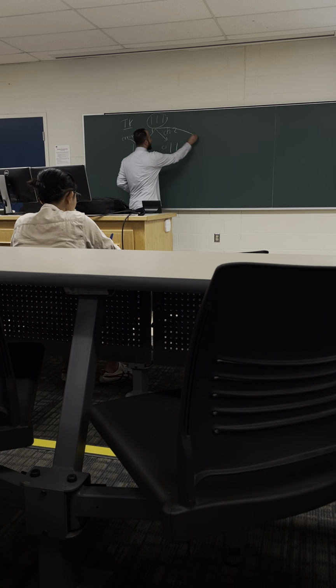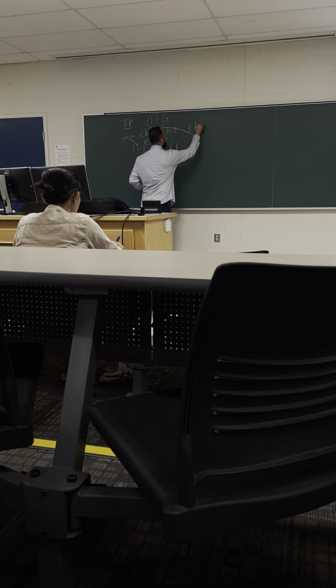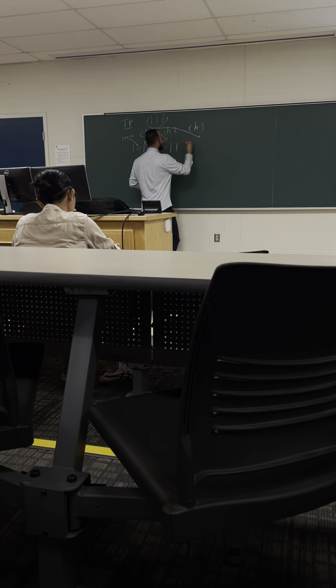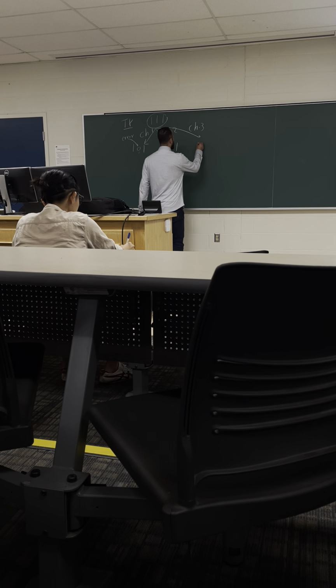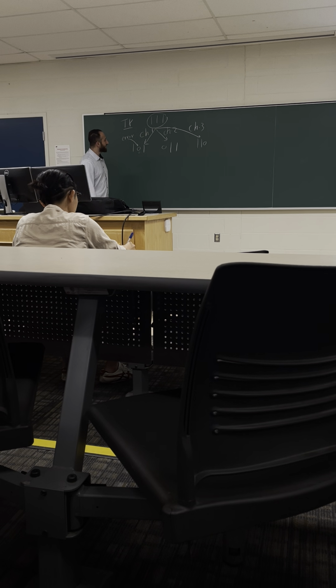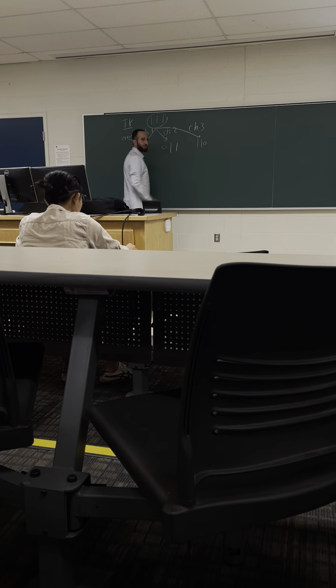And the same thing if you have a third channel, with an error different from the first and second channels, because the third channel is independent, which means the statistical behavior or the noise will be different from the first two. So you might receive the error in the third bit, okay? So instead of 1 1 1, you might receive 1 1 0, okay?